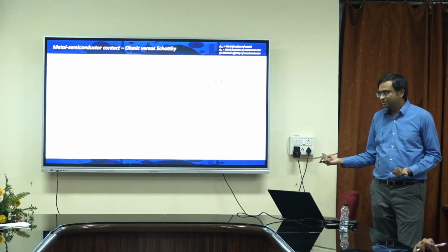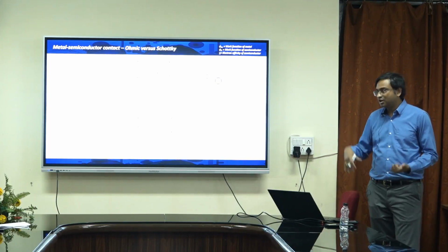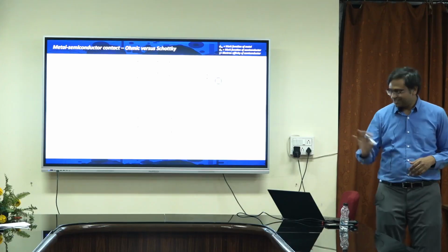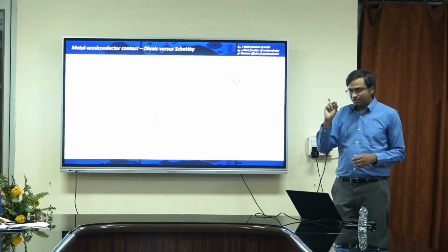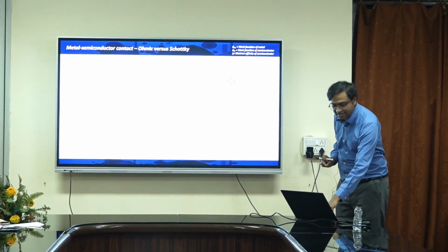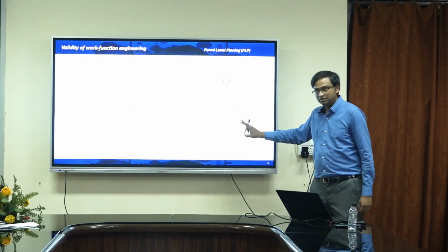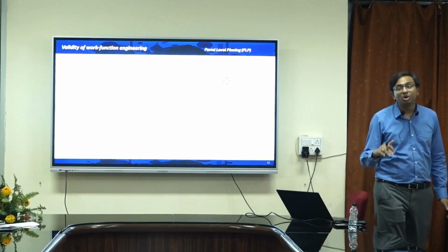You have to put the wall inside the ground so that you will be able to walk freely. Same concept, right? You need to make sure your Schottky barrier is not too big. But you have to make sure that your phi SBN is negative, right? So if chi is 3.5, your work function of the metal should be lower than 3.5.